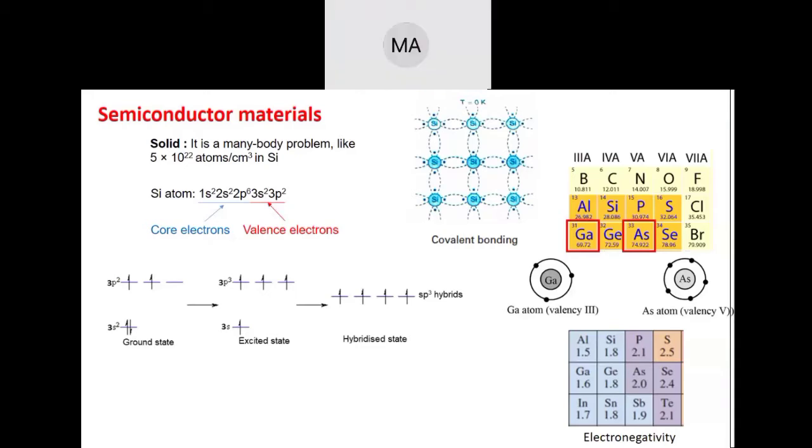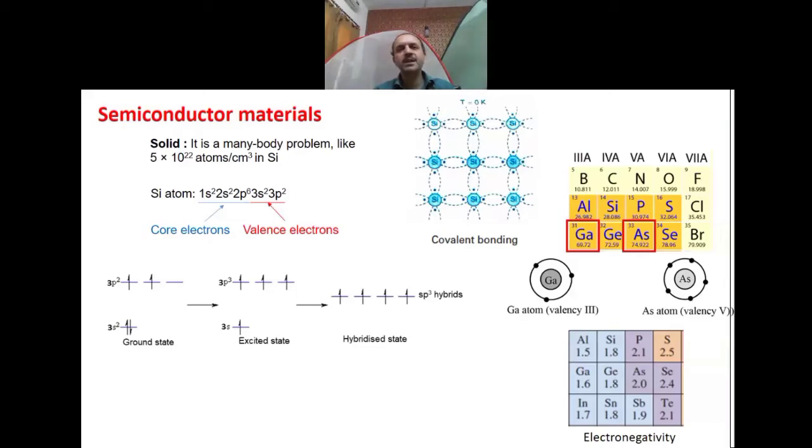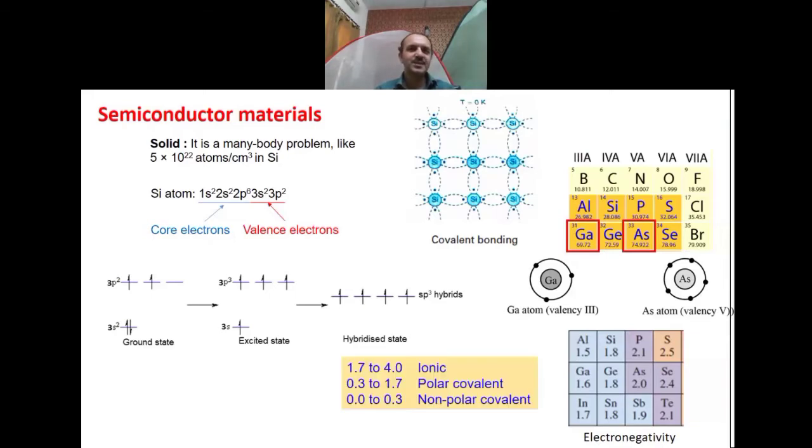So that is why when I was showing you my gallium nitride work, I showed you a 4-layer contact: titanium, aluminum, nickel, gold. And then you have to do annealing. So there is a complete process you have to develop for making a very good ohmic contact. It's not that any metal you deposit on a semiconductor, even with a low barrier height, will give a very good ohmic contact resistance. So in semiconductor technology, making a very good ohmic contact is a kind of patented technology.